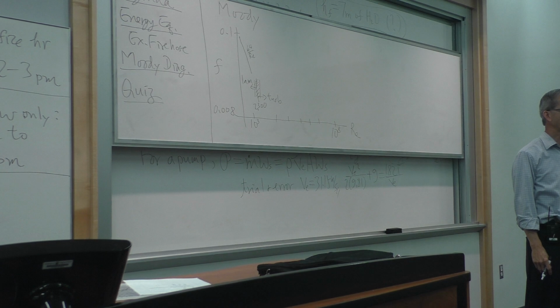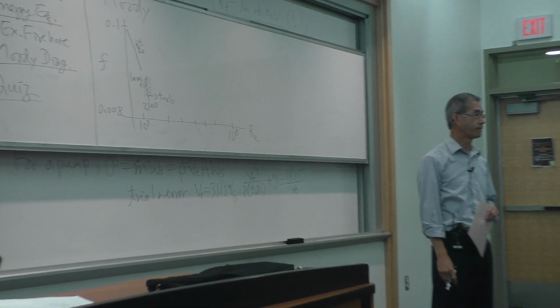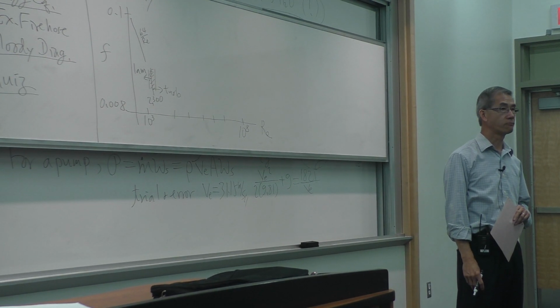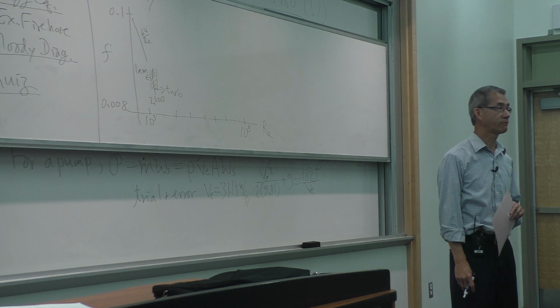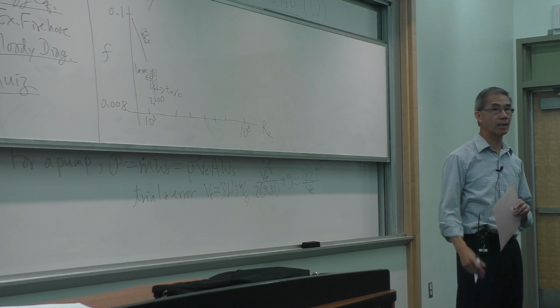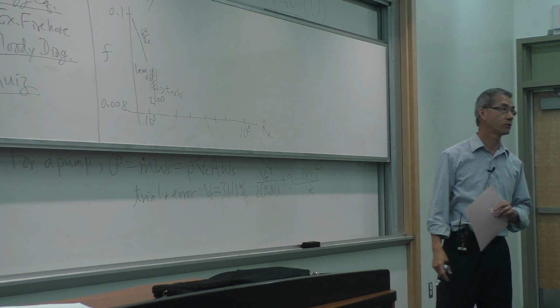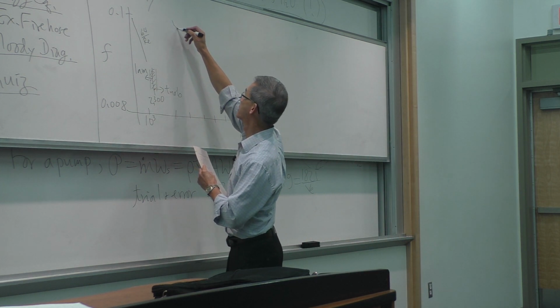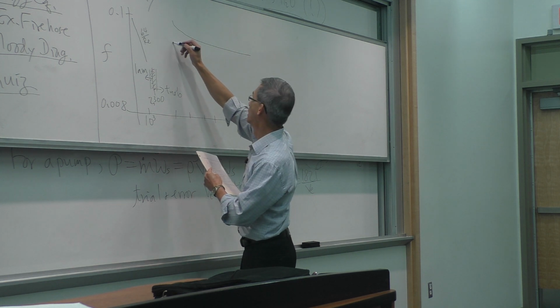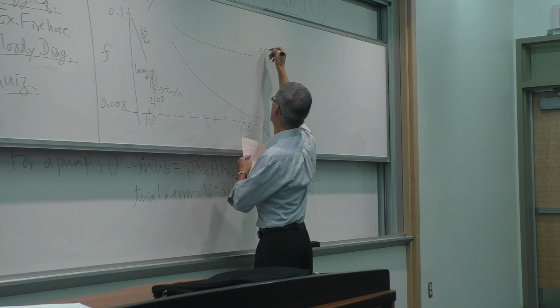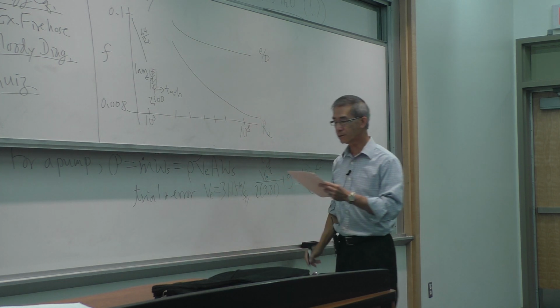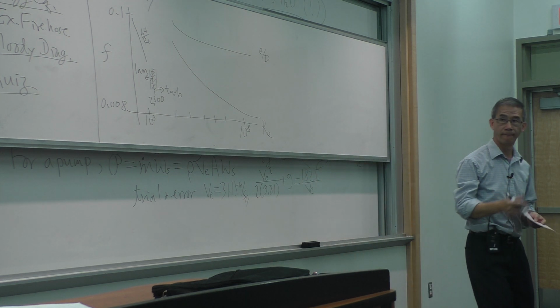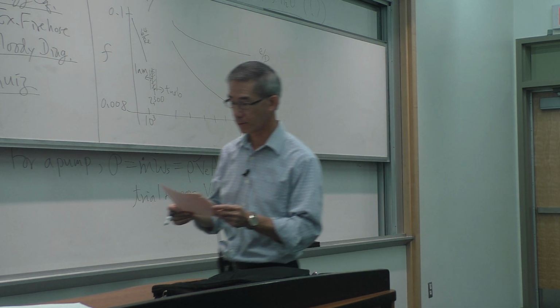How would that change something? Roughness. Yeah, roughness factor. Okay, cast iron is cheap, but it's not very smooth. So a function also that would dictate the so-called friction factor is the relative roughness, E, which is for this problem.